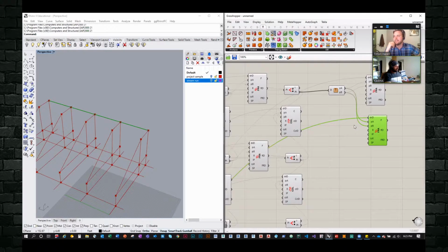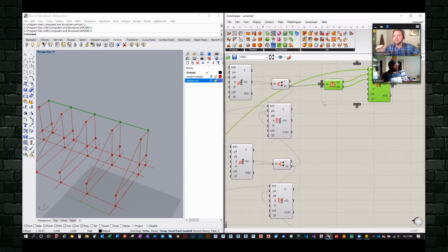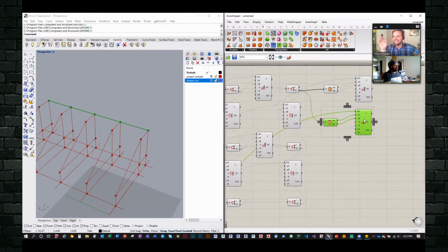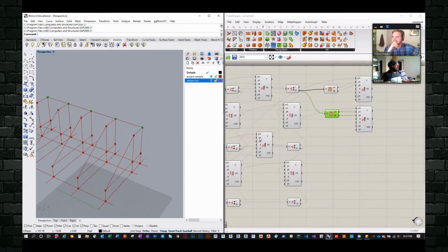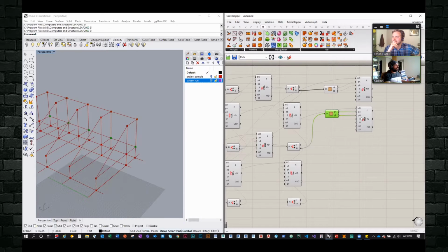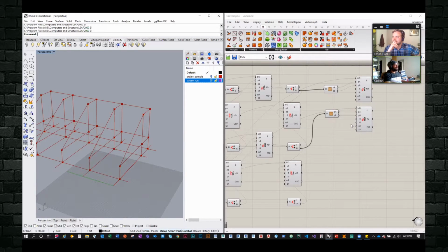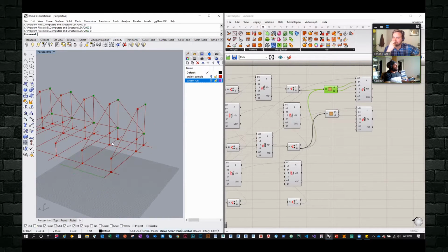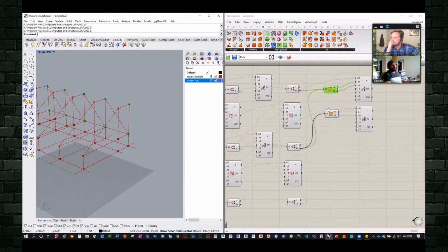How many times have I put the shift list node on there and set the settings so that it worked the way I wanted it to. And I have another cluster. Unfortunately, I couldn't remember which project I worked on. So instead of right now, where I have to plug this over and over again at each level, a lot of times these girders are typical in size and have the same section profile. So ideally I'd love to just combine another set of points into this. But obviously because of the way the points are shifted, it won't give me the exact preview.